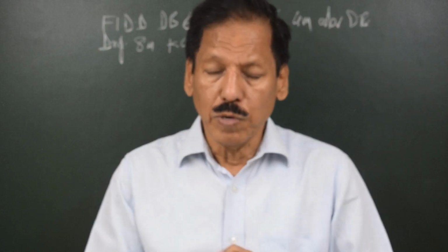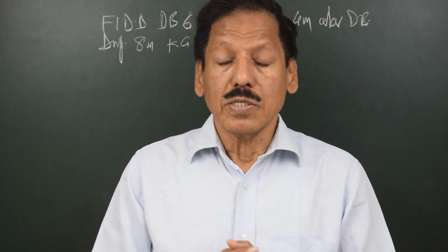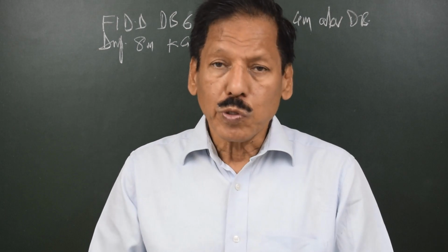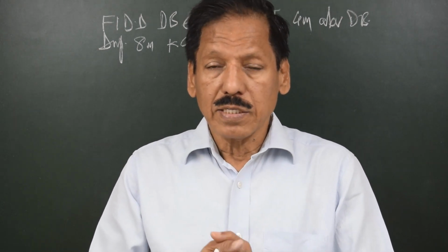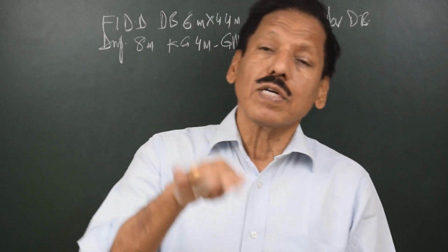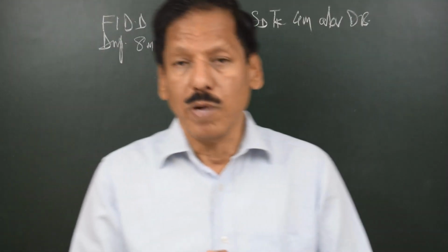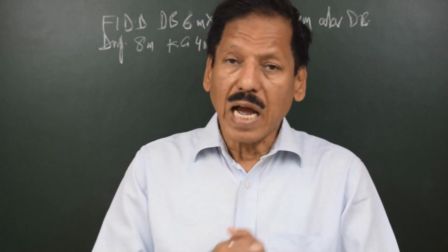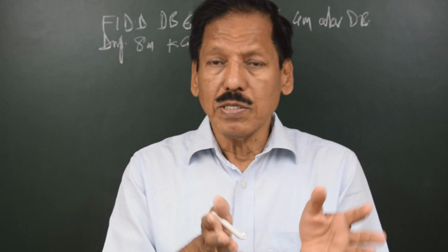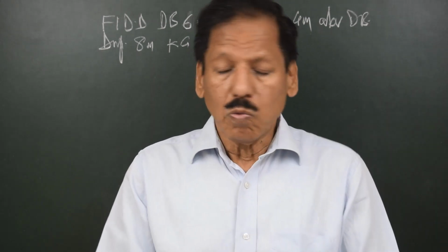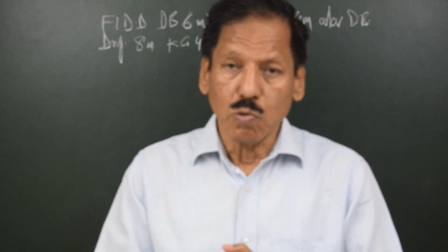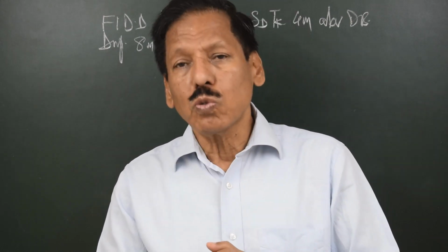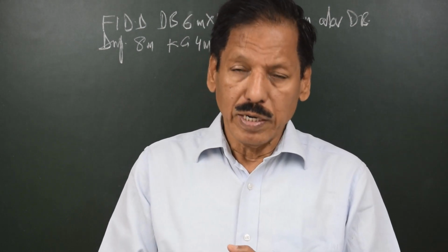BM is equal to I upon V. Suppose we talk about a craft with a rectangular waterplane, and the axis passes through the center of flotation and is a fore and aft axis. Then moment of inertia about this axis divided by underwater volume is equal to the BM transverse. For a rectangular vessel, certain dimensions get cancelled, so finally BM transverse is equal to B square upon 12D. Similarly, BM longitudinal is L square upon 12D.